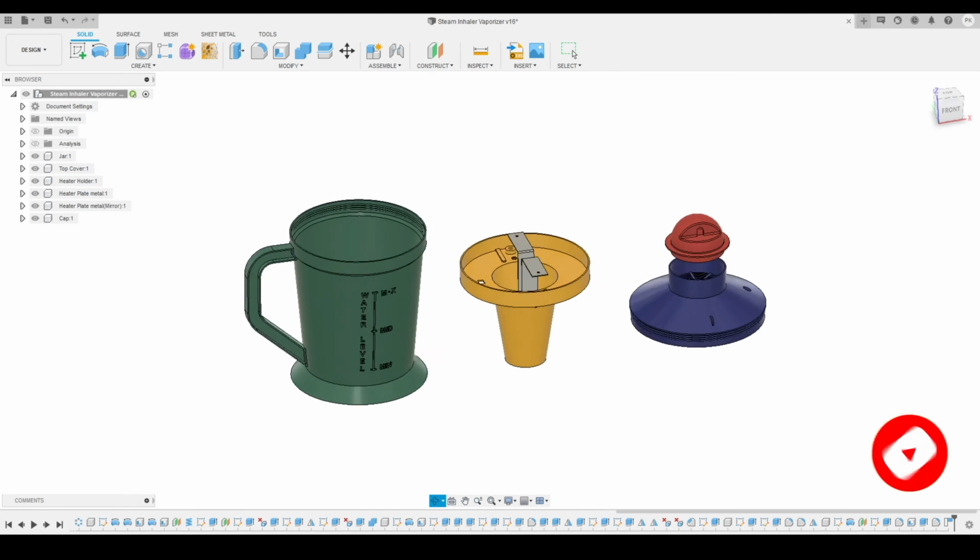You also have to make sure that you are not over defining your sketches, because that is not going to work. You only have to provide those dimensions which are necessary. Right now some entities in my sketch are still blue because I had not defined my sketch 100%. Whatever line is completely defined turns black. So our target is always to define every piece of components.